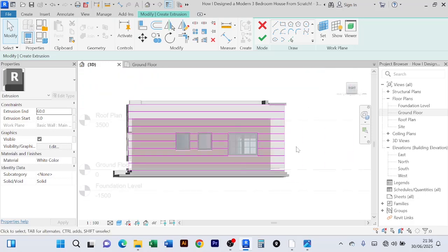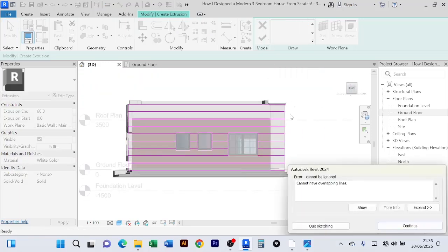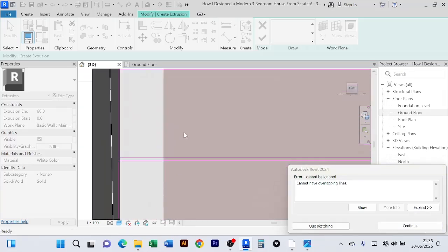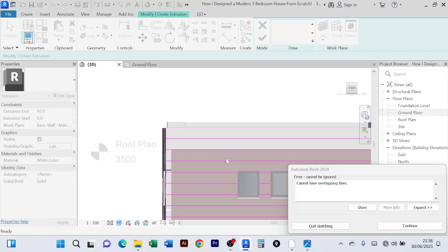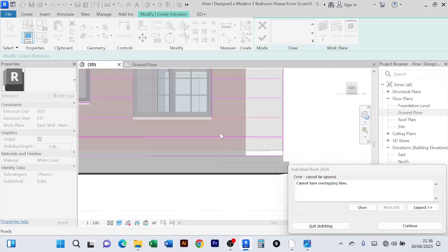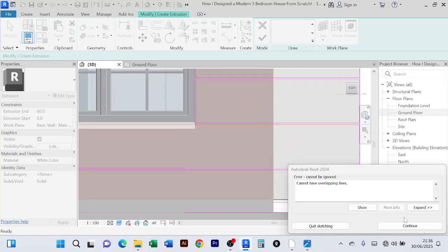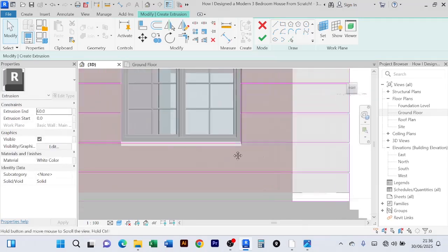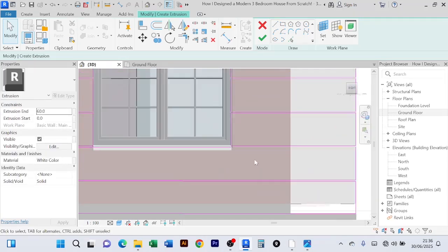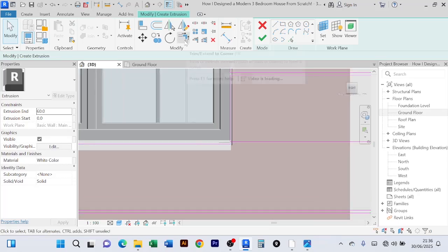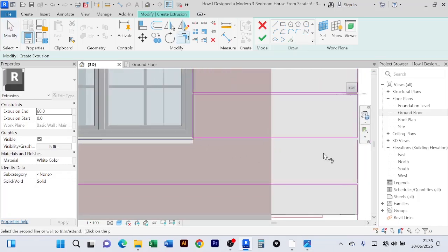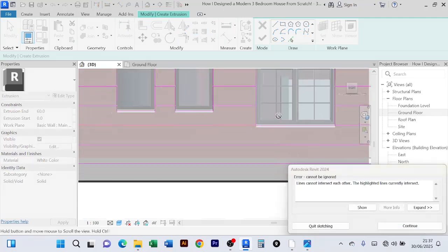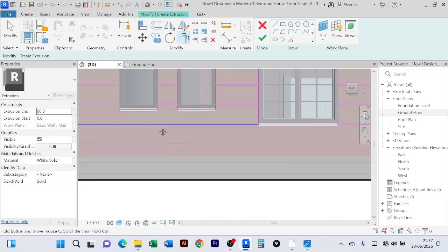So let's try and finish the model. Revit is complaining. That means there's somewhere that will not link up the lines. Is this one here. So we click on continue. If I delete that, you realize we have more lines here. So we shall come to trim. We shall extend it to this part. To finish, still an issue, continue.